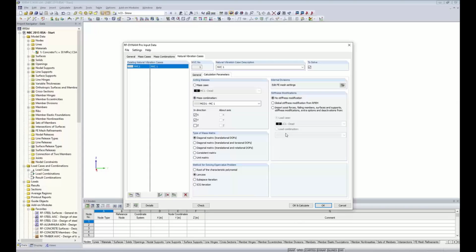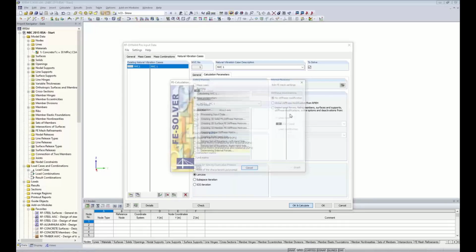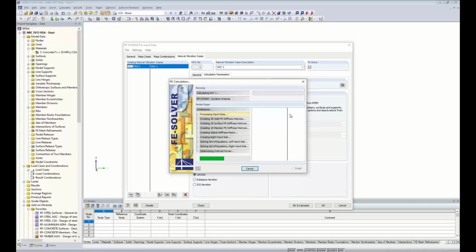And in my previous webinar, according to the ASCE 7 for a response spectra method, I did show how to consider a P delta analysis. So again, you can refer to that recorded webinar on our YouTube channel or website. But for today, we won't be applying any of these settings. We'll just leave this as no stiffness modifications.